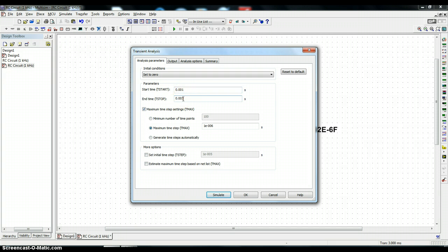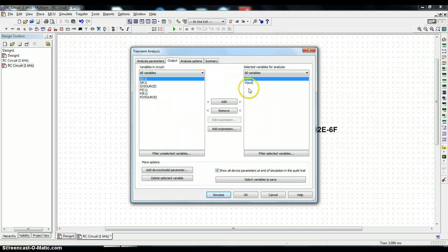And I'm running it initially over 2 cycles, so it's running from 1 to 3, so we can take at least an initial view of the output signal. The time step is actually down at 1 microsecond, which should give it very good accuracy. And we set the initial condition to 0, meaning the capacitor voltage is starting out with 0 voltage. Let's check the quantities for the output. I've already put in V in and V out, the input voltage and the output voltage.